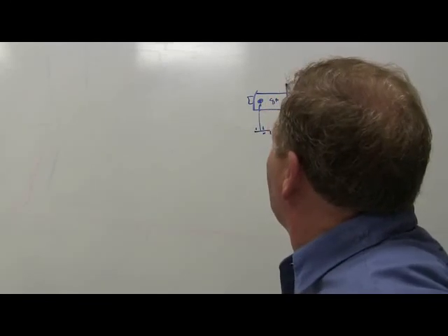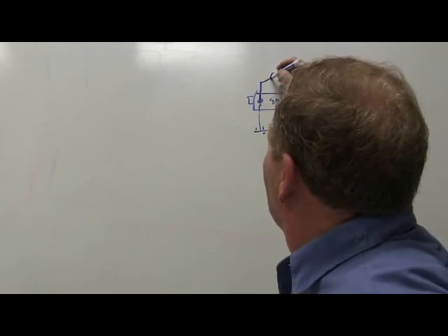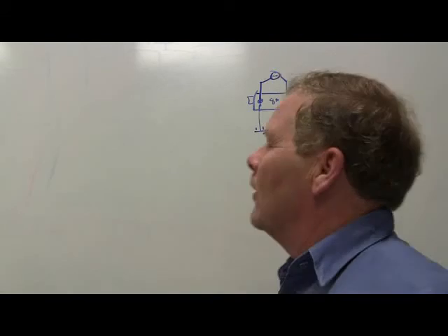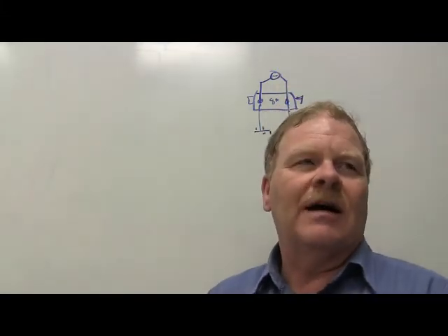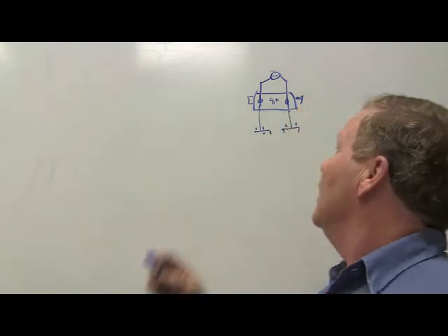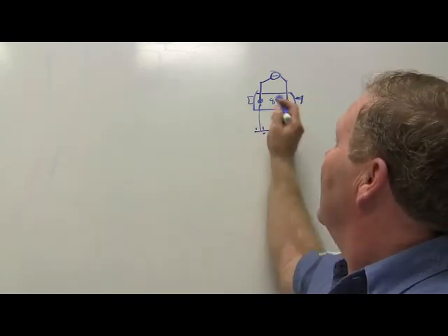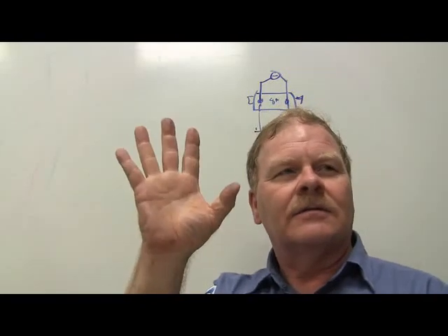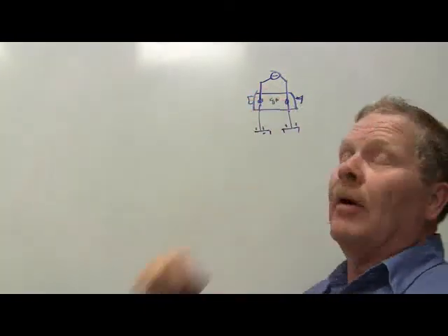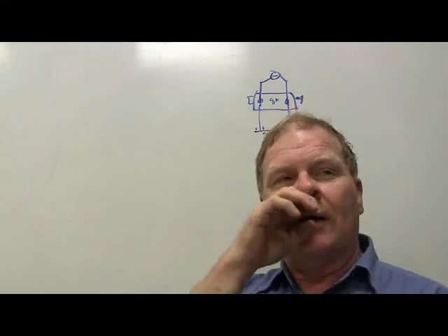And I'm going to take a little light bulb and put it right here. I'm going to build me a tool. It's almost a freebie. You've got to buy the circuit breaker and find your light bulb somewhere. You go in there like that. That circuit breaker is going to click off and on. Ding, ding. When it opens up, that light's going to be burning. When it closes, that light will be off.